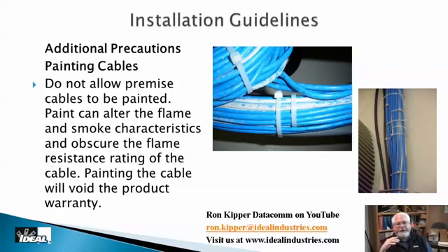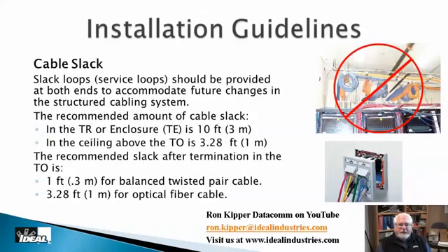So just be aware of, again, try not to leave them exposed, because eventually they will get painted. I can almost guarantee it. Now, cable slack at either the telecommunication outlet or back in a telecommunications room has changed from what we used to think about 15, 20 years ago. Today, the standards basically recommend that if you're in a telecommunications rack, no more than 10 feet of cable, or about 3 meters, is left coiled up above the rack someplace, for moves, adds, and changes that might happen somewhere down the road.